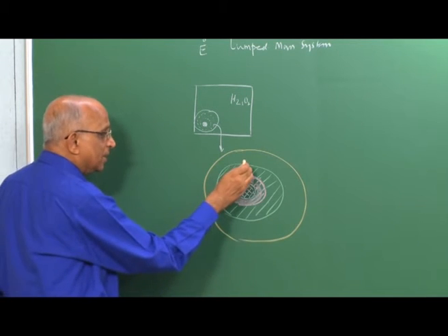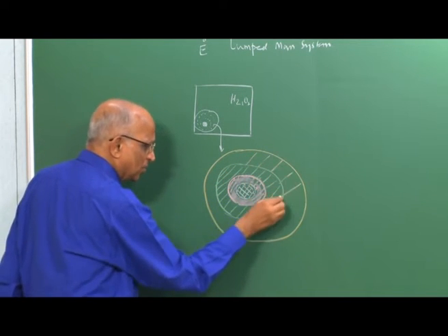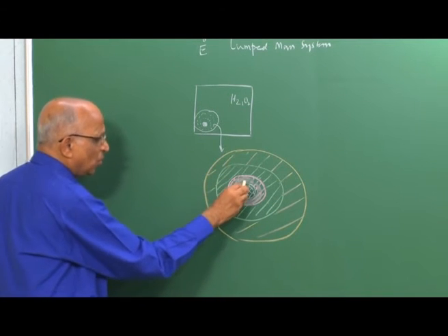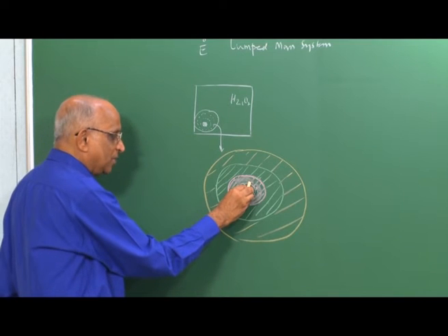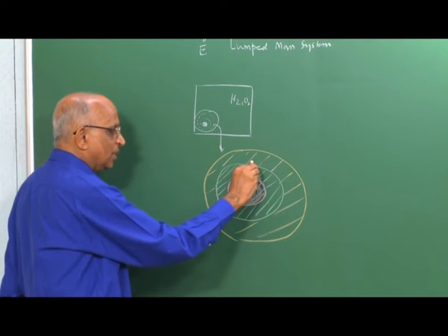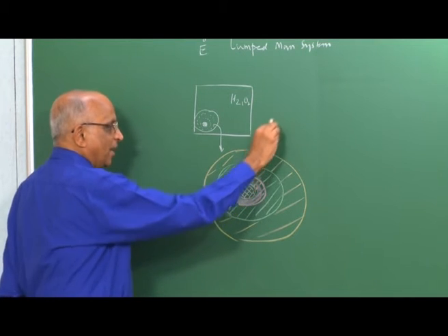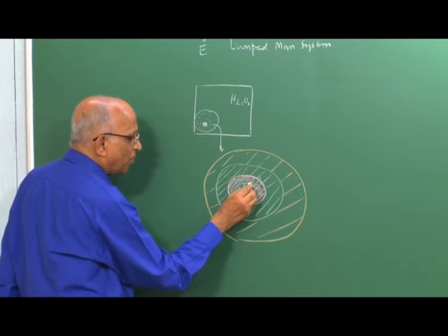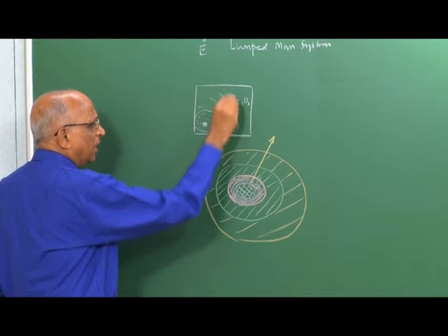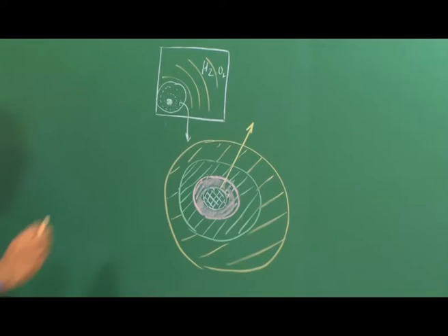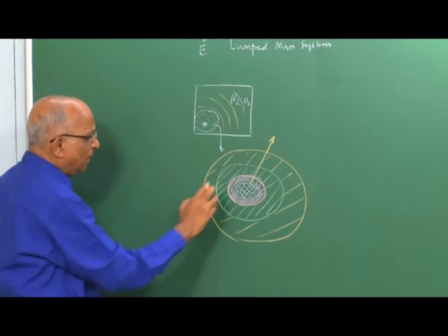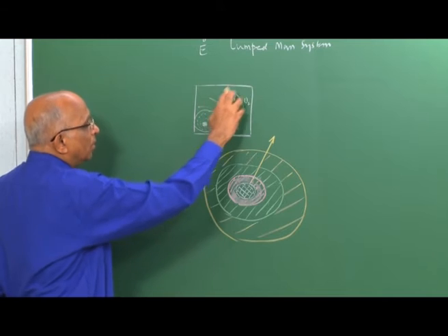And therefore, what is happening? This zone heats up the zone adjacent to it, and in this way, from this initial zone of heat release, you have chemical reactions occurring because of heating. It causes chemical reactions in the next layer, and in the next layer, and so on. You have chemical reactions propagating out from this zone of heat release till it fills the mixture. Therefore, it is not that instantaneously, as assumed in the lump mass system, everything is uniform, but it is going to take some time for it to propagate out.